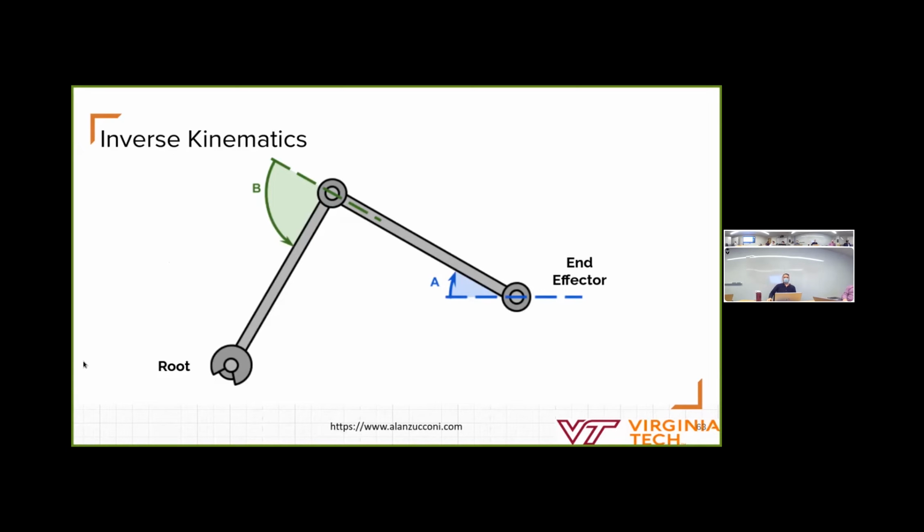So why would you want to know that? Say you have a robot arm and you need to know where in 3D position that robot arm is. If you have sensors on all the joints and you know the length of all the segments, you can calculate very precisely where that point is. The inverse of that is, say we have this robot arm and we want it to be in a specific position, and we need to know what the joint angles, and possibly the length of the linkages if that's something we can modify, need to be in order to achieve that.